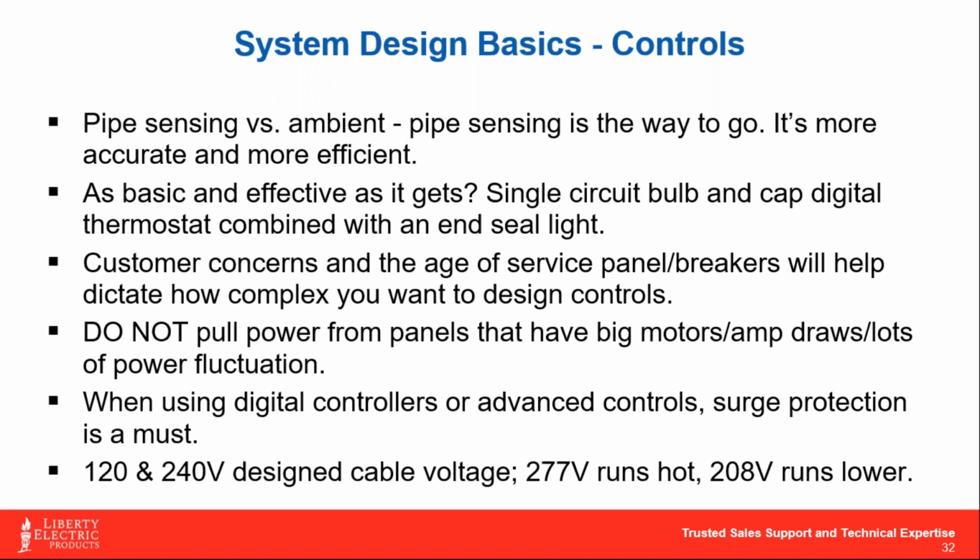When we talk about pipe sensing versus ambient, it's not that ambient is wrong by any stretch. We just feel that skin, pipe sensing is going to be more accurate. It's usually going to lead to your heat cable being on less than it would for an ambient system, which over time can matter. If we're letting these systems run flat out, voltage is essentially what winds up degrading the self-regulating carbon mastic, which gives you all that flexibility. So over time, if we can keep some cycles off it, that's not a bad thing. It's not huge, but by the same token, it can make a difference.